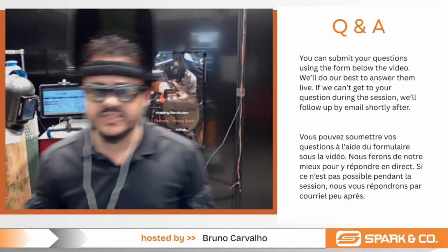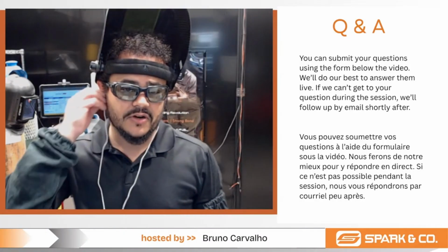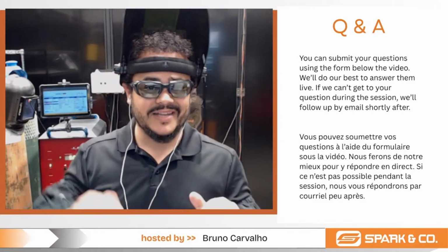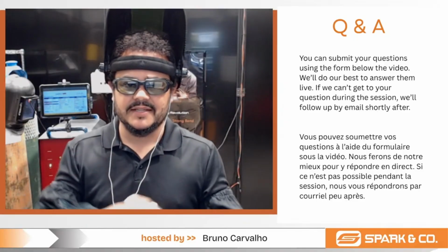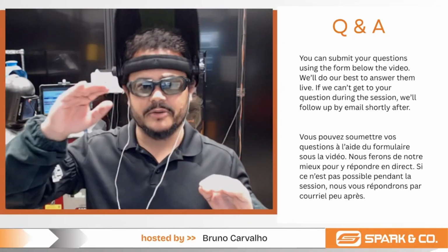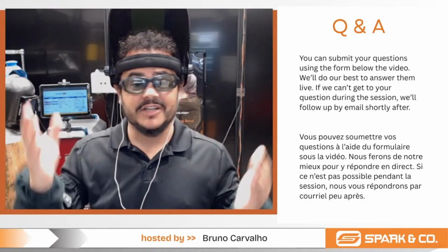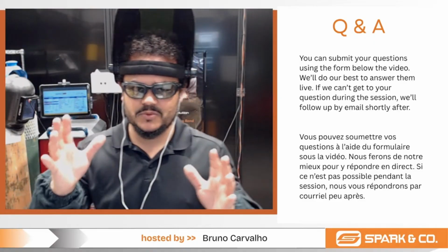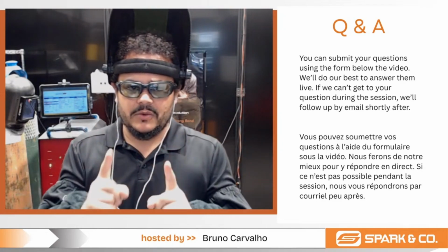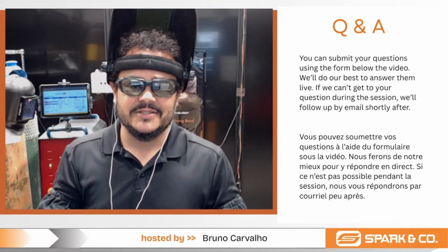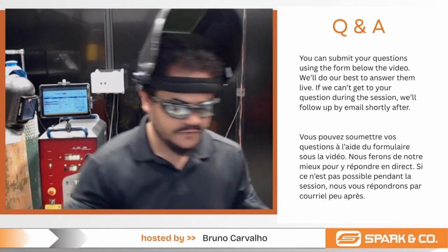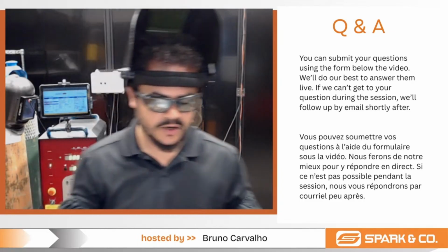So what I understand so far is that you're reducing the power and having the same amount of penetration. That means that when you're putting your machine at the maximum, you are not seeing any difference, right? In this case, you need to play with the frequency. You need to adjust the frequency. If we check on your recipe card,